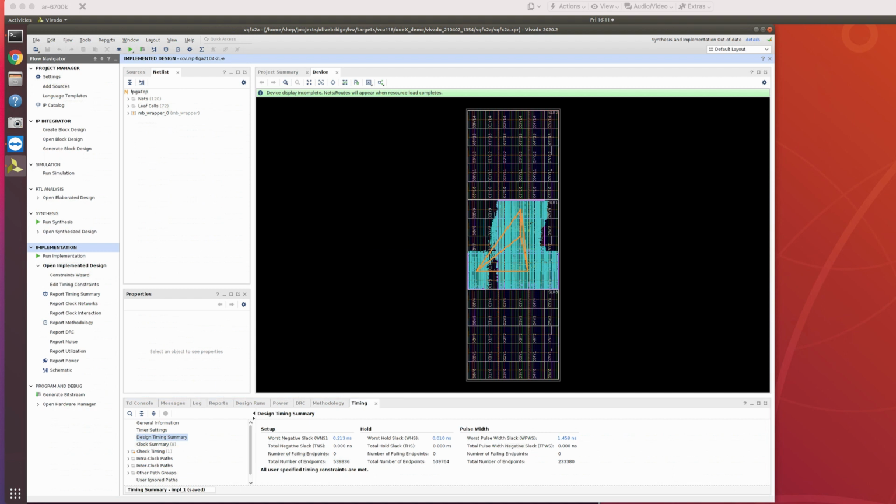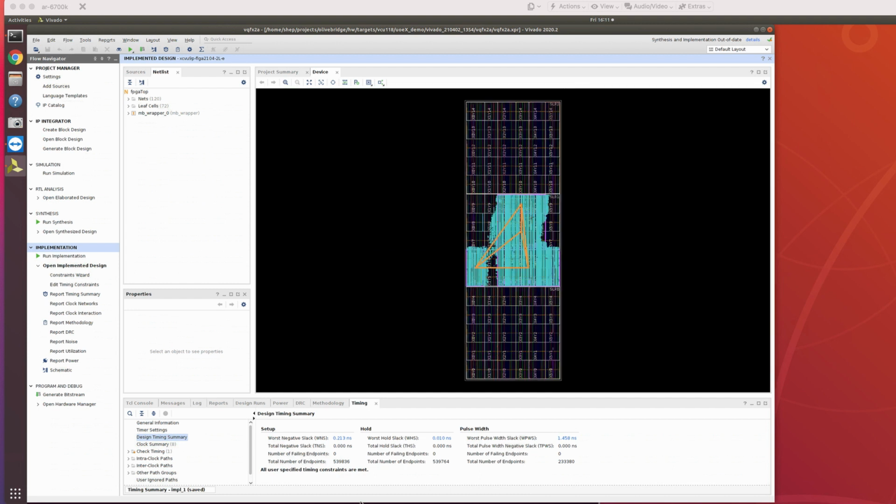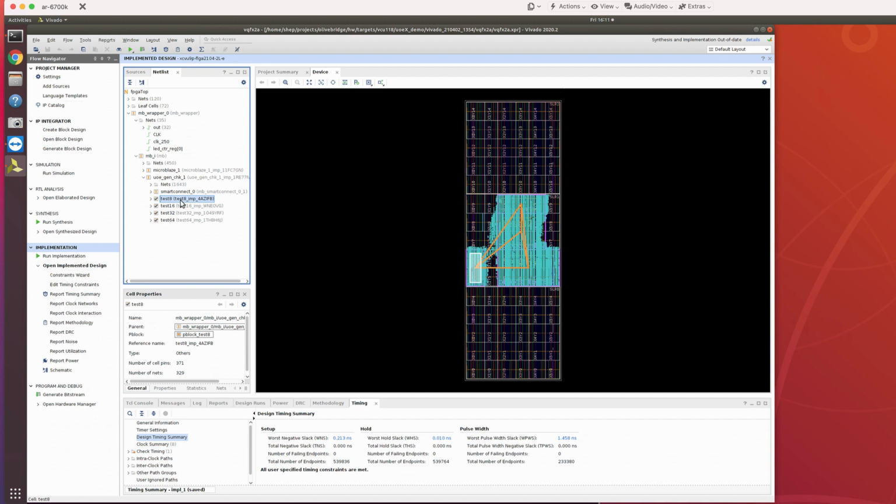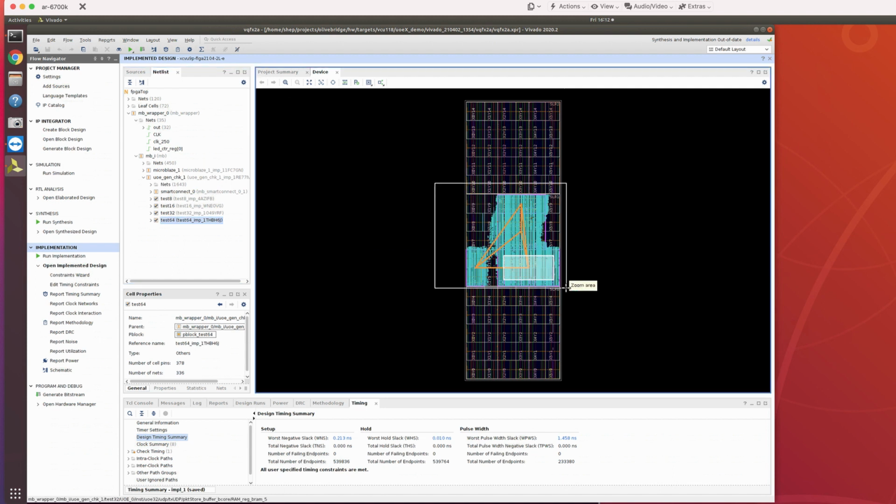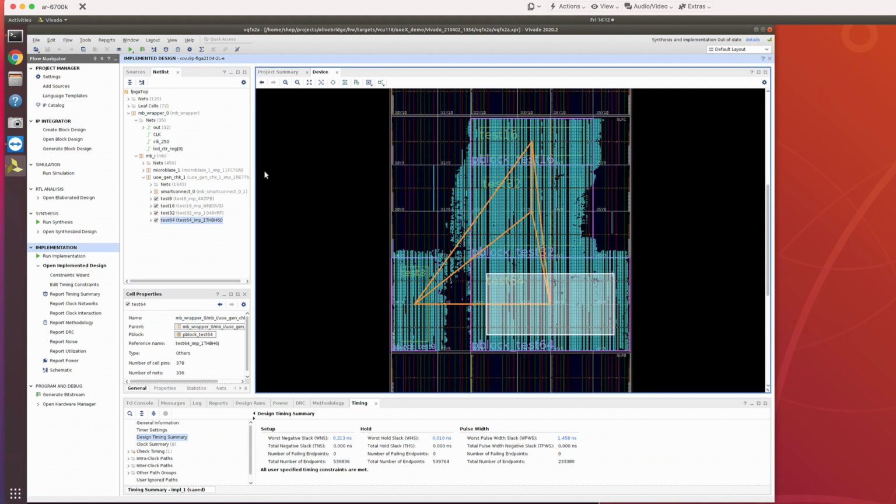So this shows the implemented design of the 4 UDP offload engines that are present on the uoeX example design. We can take a peek to see what area they use by expanding the subsystems here. We see we have an 8-byte, a 16-byte, a 32-byte, and a 64-byte design. You can see all the designs are in the center SLR of the 3 SLRs in this VU9P device. This happens to be on a VCU118, but it could just as well be on a U200.